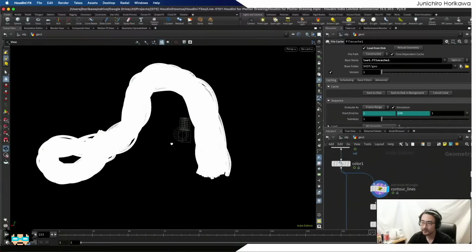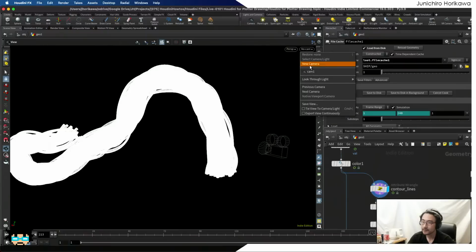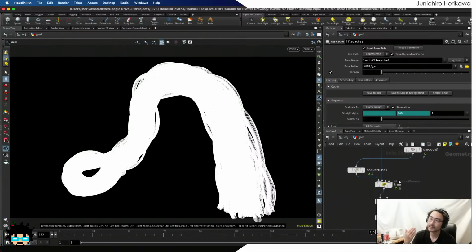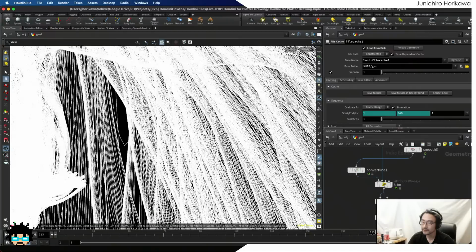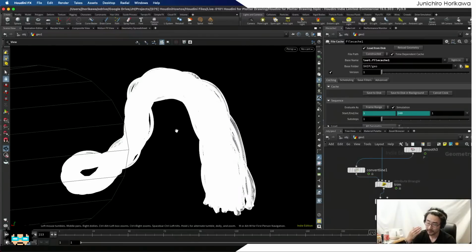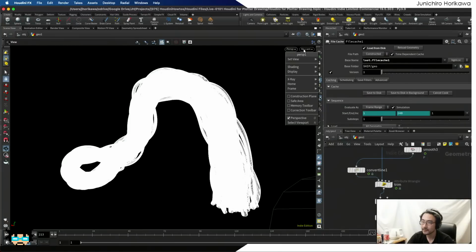I'm going to do that using specific camera information. From this camera view, what I first need to do is trim out the backside of the curve. As you can see, there is also a backside of the curve being drawn. We don't want to send that as a drawing, because it's going to be really busy and messy when you draw the backside as well.